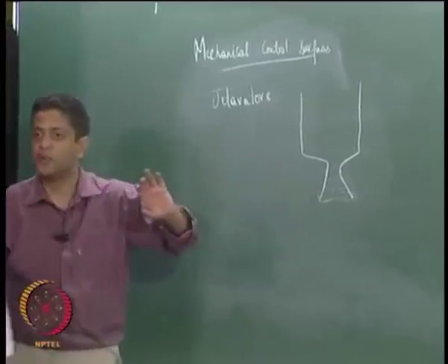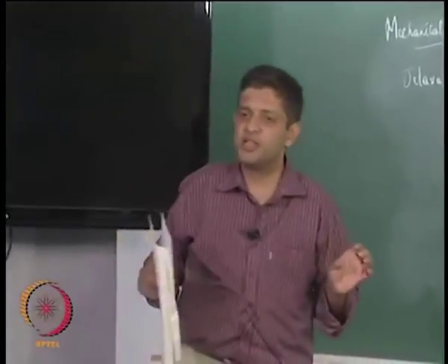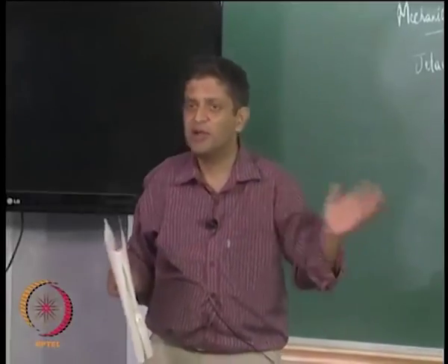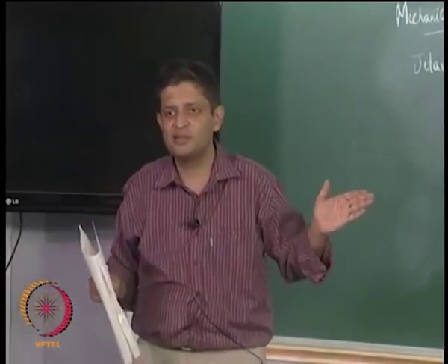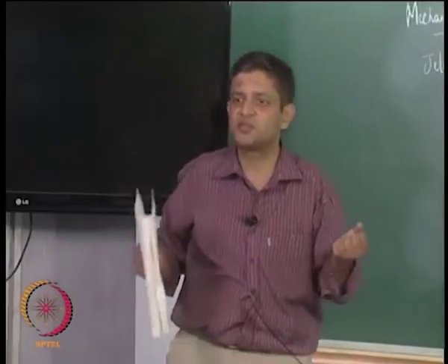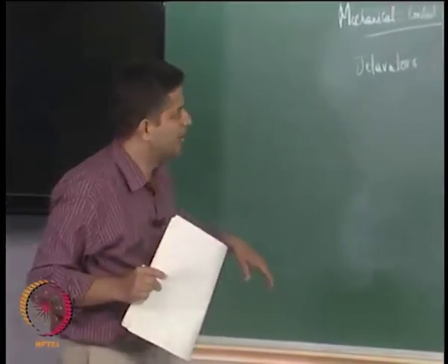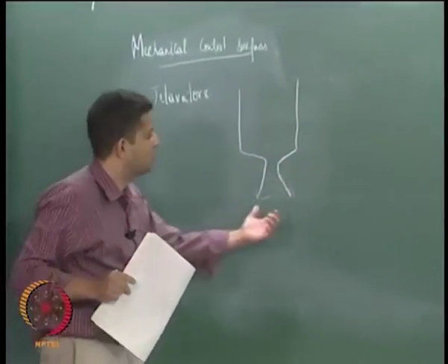So, this does not protrude into the flow in its normal position, but when you change its position, on one side you get over expansion and on the other side you get a little bit of under expansion. This causes a side force. Okay. So, you are going to get a small amount of thrust vectoring.